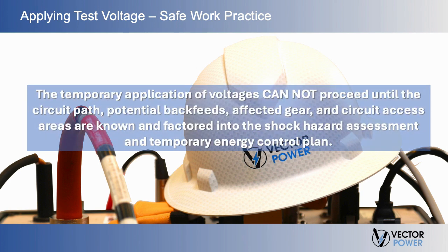The temporary application of voltages cannot proceed until the circuit path, potential backfeeds, affected gear, and circuit access areas are known and factored into the shock hazard assessment and temporary energy control plan.